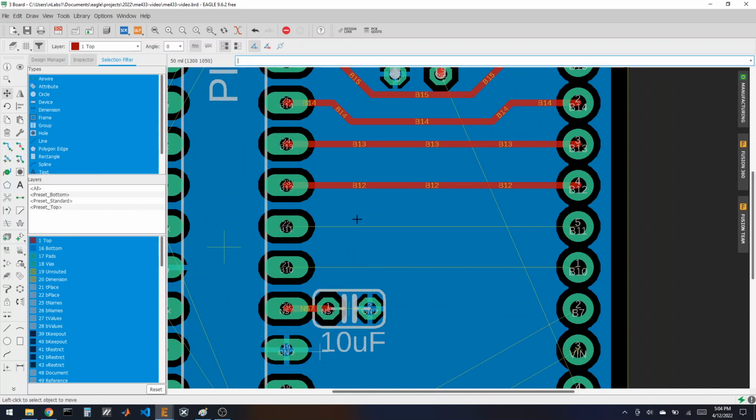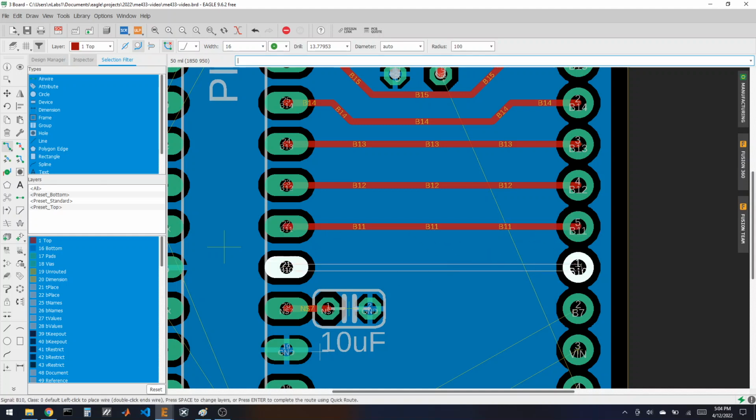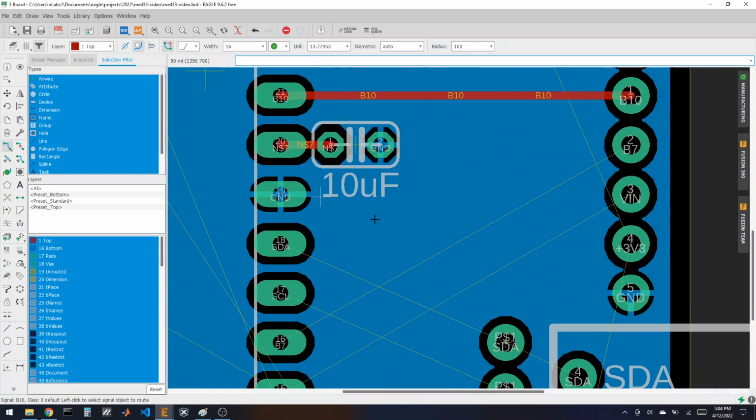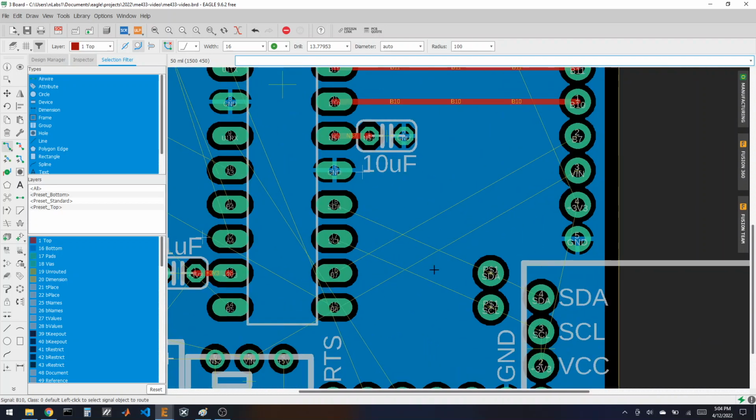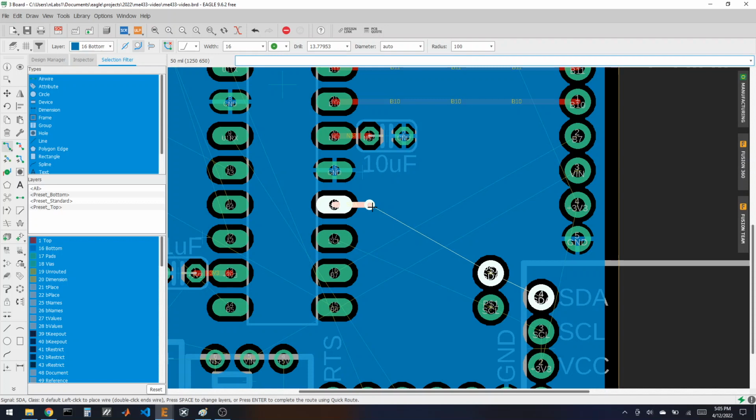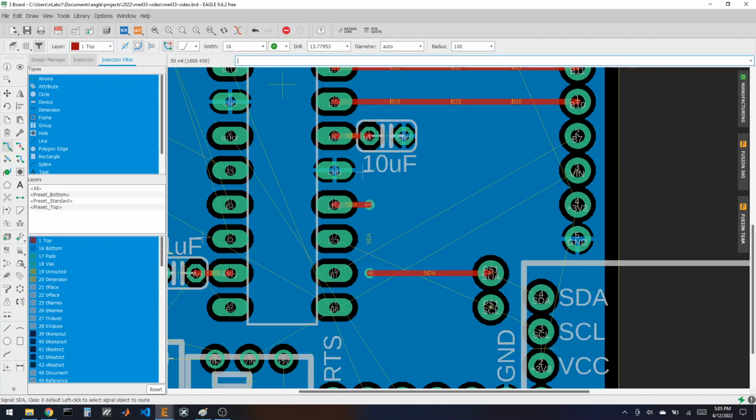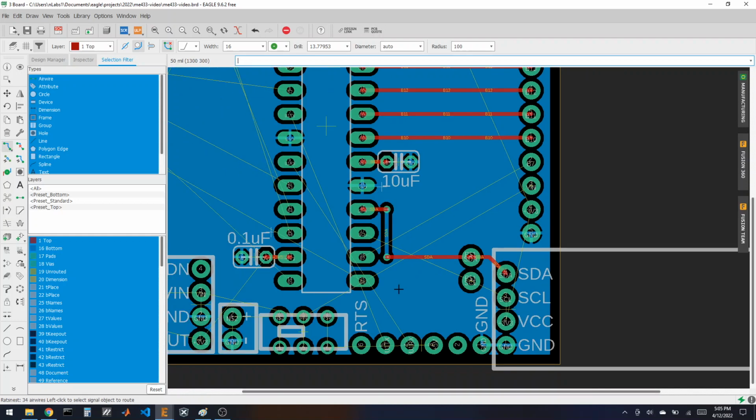Okay. Keep routing wires. Okay, here's some good crisscrosses. So these guys need to end up down here, but these need to end up there. So what we want to do is go across, and at some point switch to going down. Switch back to the top layer, finish them off, and use the rat's nest to show that that's no longer a ground.